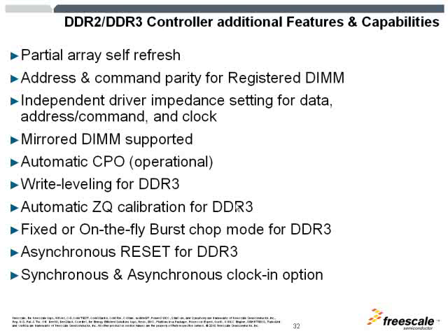Then there's the feature of providing the automatic ZQ calibration for DDR3. This is a specific feature for DDR3 that is not available in DDR2. This feature was added into JEDEC for DDR3, where you could dynamically calibrate the driver strength of the SDRAM.